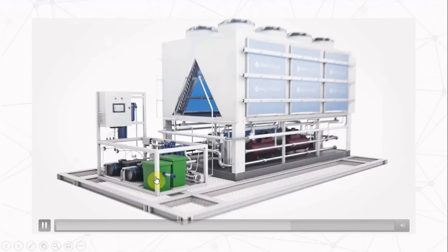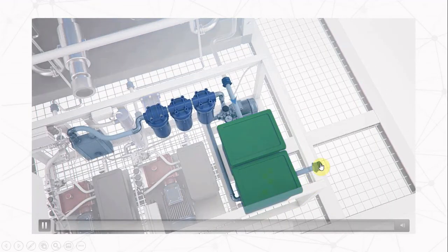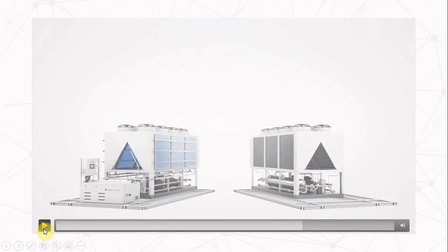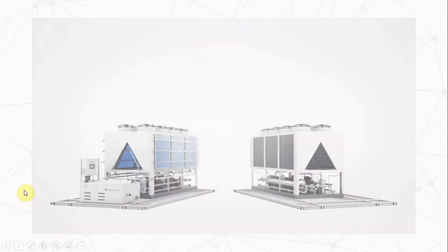From the drainage profile, the water is distributed back into the Smart Cooling recirculation kit, where the water is recycled by 5 different filters. The water is cleaned from all mechanical dirt and then passes through the electromagnetic filter, the limescale treatment, and the UV radiation lamp. Only after this, the water is reintroduced back into the system.